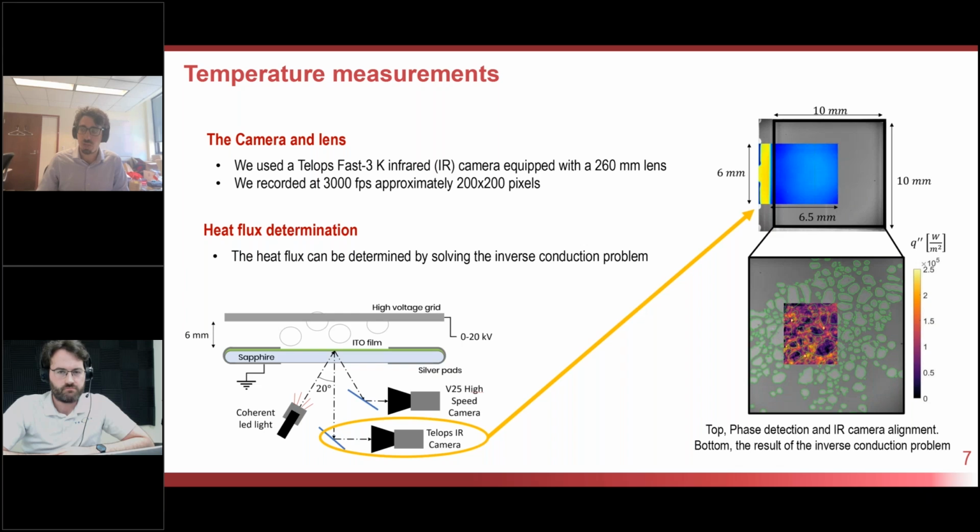Especially if we have heat transfer, I bet that we're going to have a lot of image deformation, I guess, because if the liquid has different temperature, it has a different index of refraction, and so you have aberration of the image, right? That makes sense. Yeah. But it depends on the application, I feel it might be very, very difficult to do that kind of measurement. Anthony, what do you think? You're probably more expert than me in this.